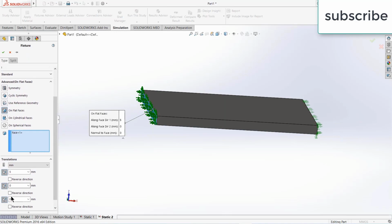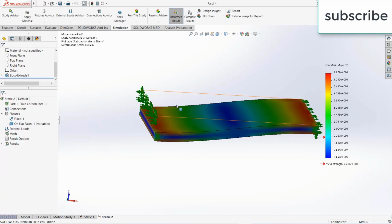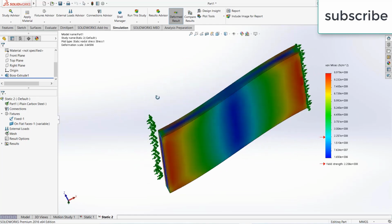When I put 0 mm and 0 mm, it means that it can move downwards, but there can't be any kind of movement in this direction and in this direction. So basically it can't compress and it can't shear. Okay, that is the reason I got this kind of stress.